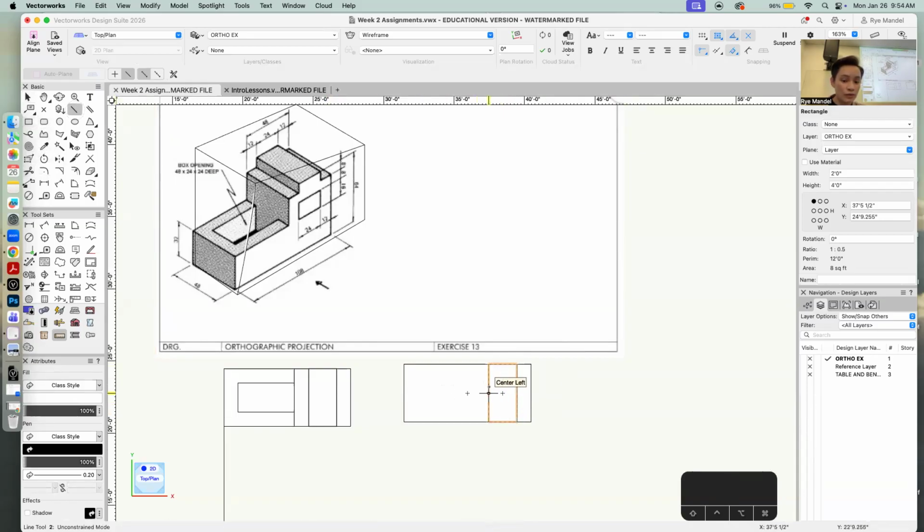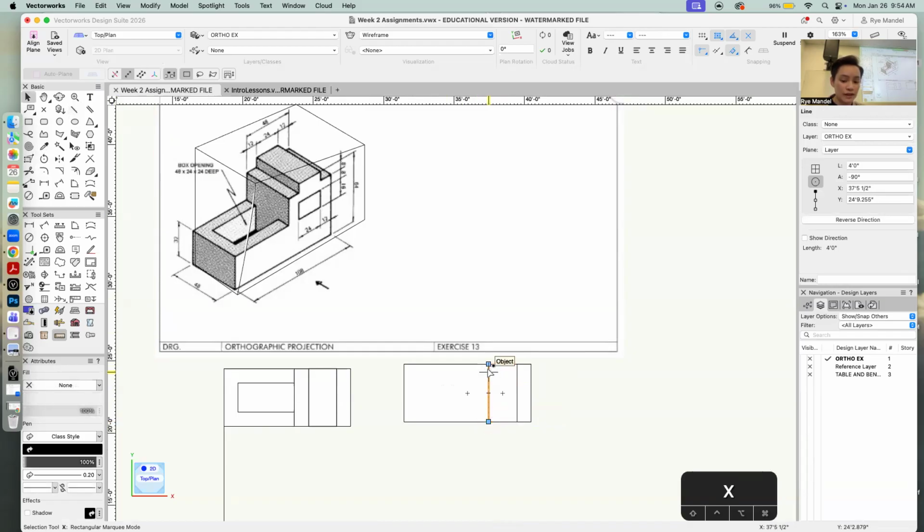I'm going to draw one more line just over this, and then I'm going to move it by sliding it over. It's 12 inches over because that's the dimension that I'm seeing. Then I'm going to hit shift so I know that it snaps to it. And that's how I got this line. So that's how we took care of this whole piece, right?